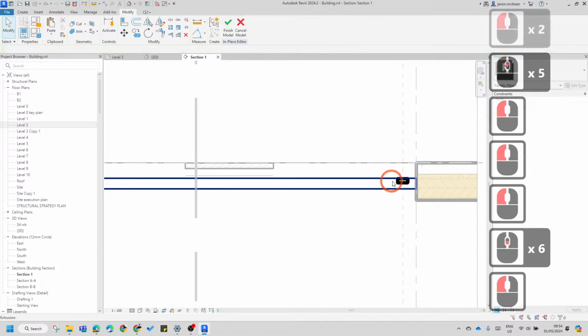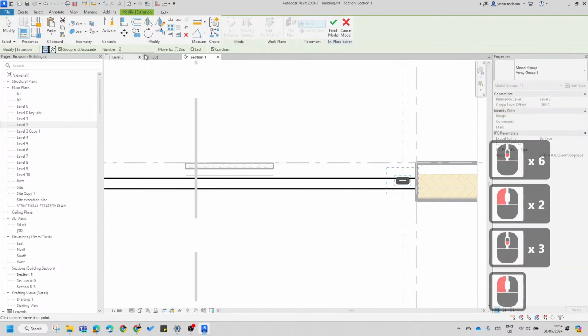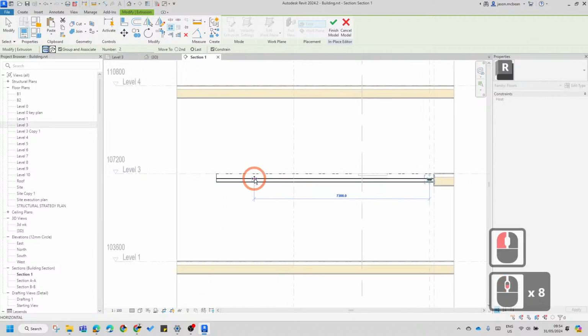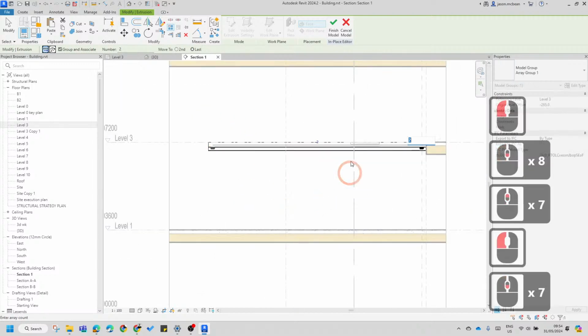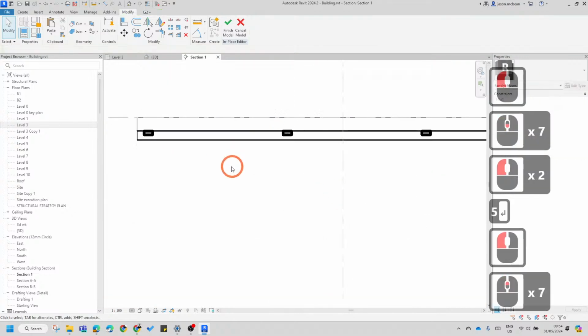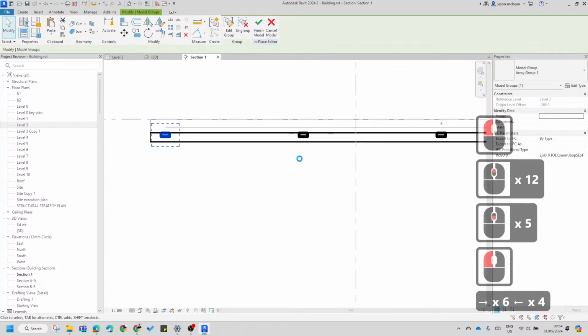The controls work better. Now watch this. You're going to create an extrusion. I'm going to say from here to last. I'll explain why. So from center to center, last. It means if this one changes, watch. They all move.